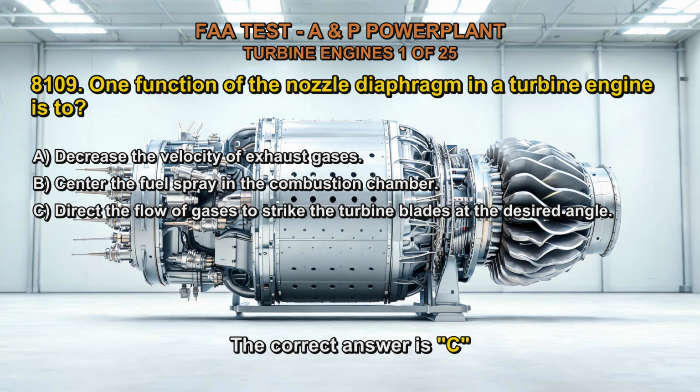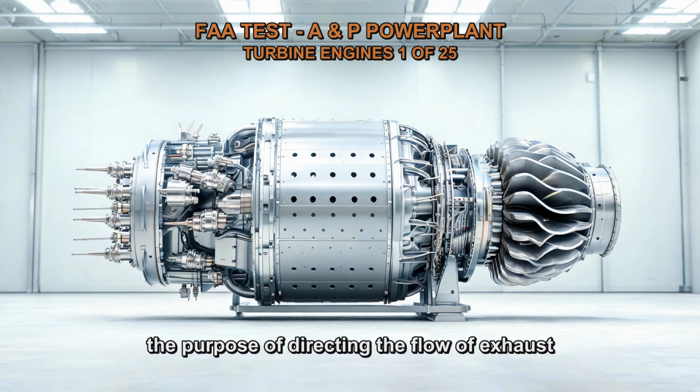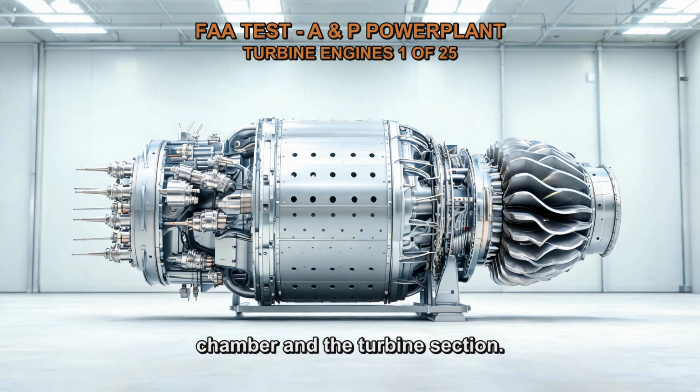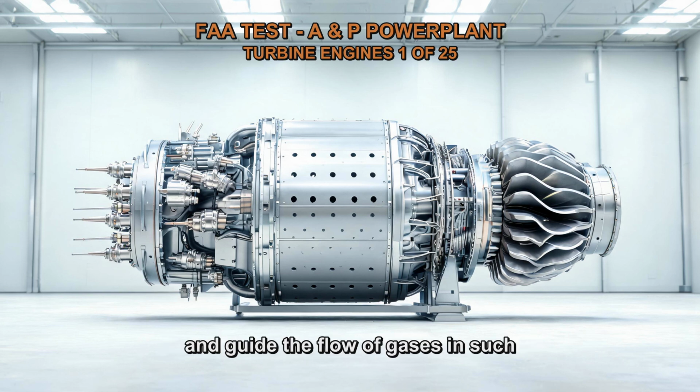The correct answer is C. In a turbine engine, the nozzle diaphragm serves the purpose of directing the flow of exhaust gases from the combustion chamber towards the turbine blades. The nozzle diaphragm is positioned between the combustion chamber and the turbine section. One of its primary functions is to control and guide the flow of gases in such a way that they impinge on the turbine blades at the desired angle.